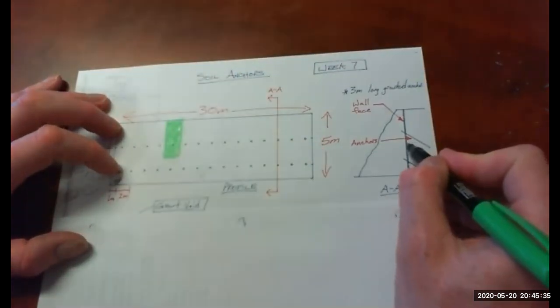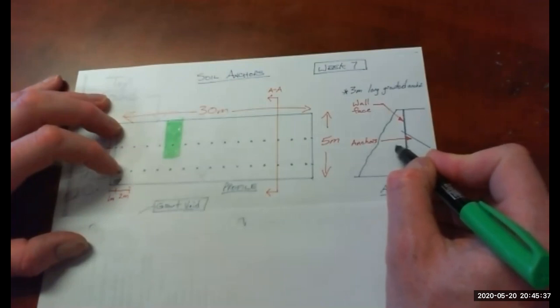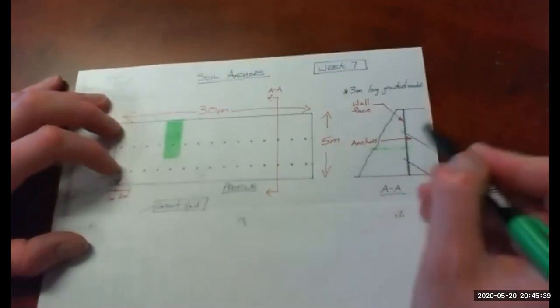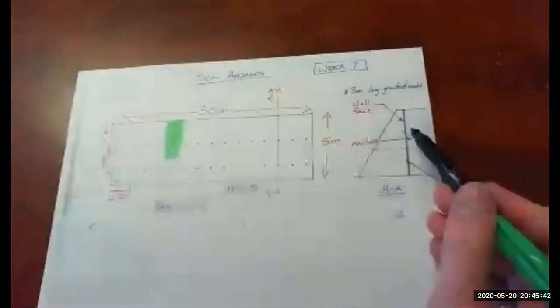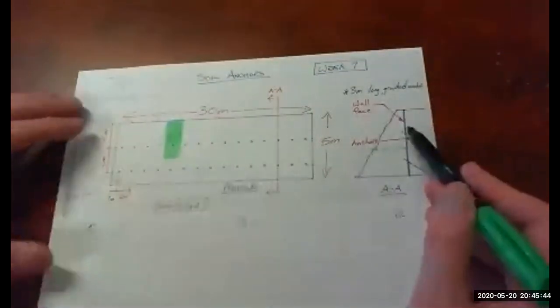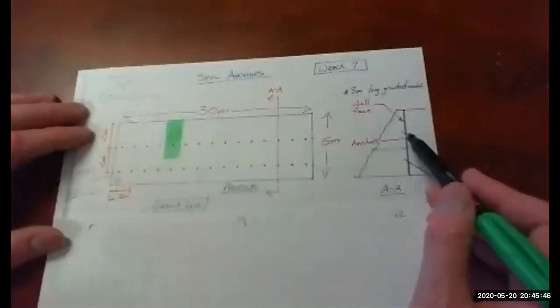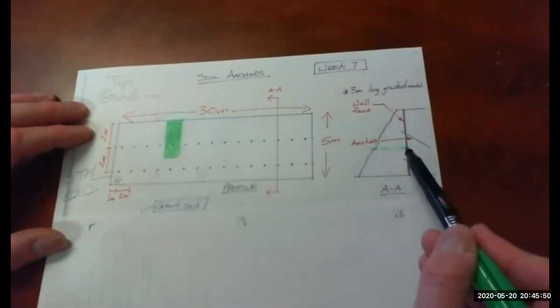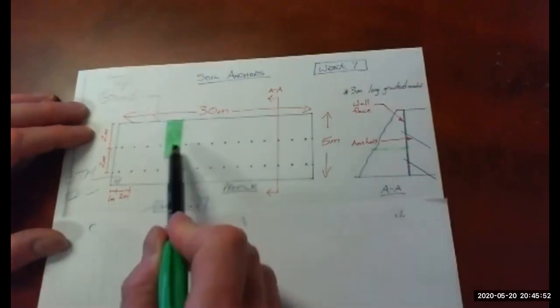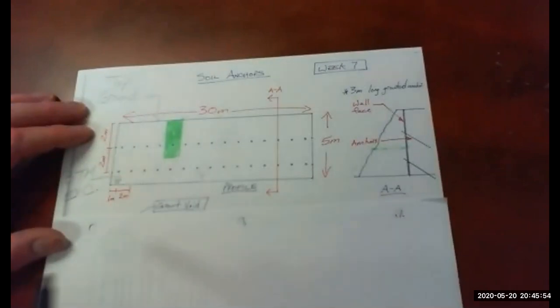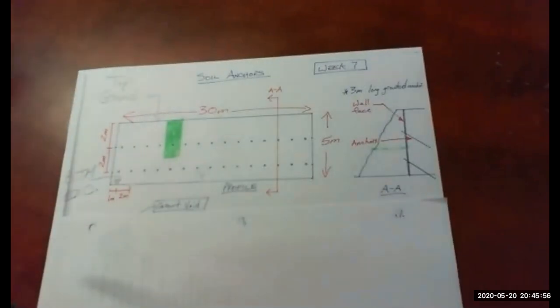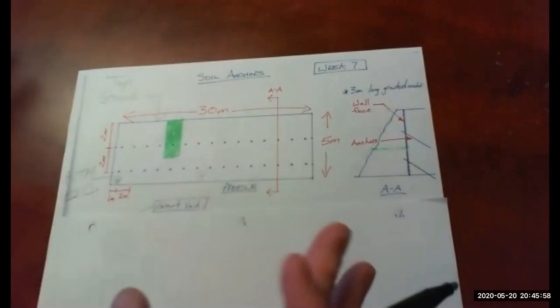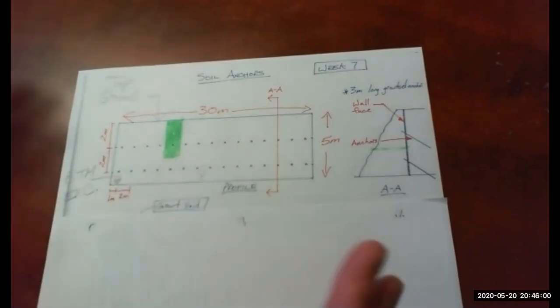So if we showed that here, you'd come down approximately halfway between your 2 rows. That would be your depth down. And then you would go halfway between each anchor on either side, where the design anchor is supposed to be. Now remember, we haven't put any anchors in yet. We're only excavating first.